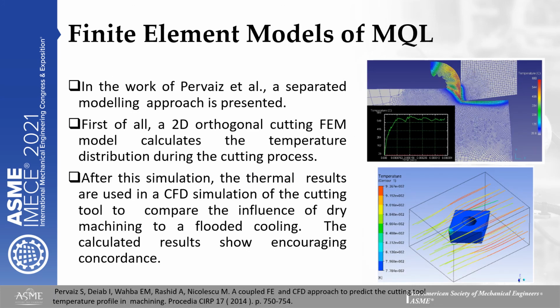In order to address the problem, there are some approaches recommended in the literature. For example, in the current approach, a two-step method is utilized. In the first step, a 2D orthogonal cutting finite element model was developed that provided the temperature distribution. In the second step, the temperature was used in a CFD simulation, and the interaction of cutting fluid, which is basically in this case dry air, was modeled using the CFD approach. The approach provided very encouraging results.